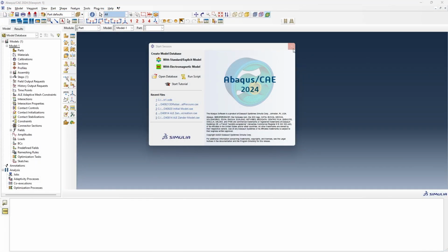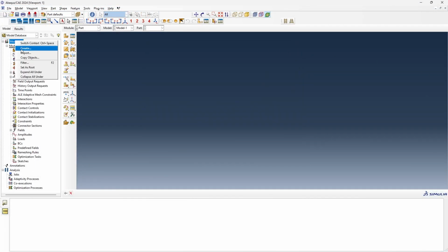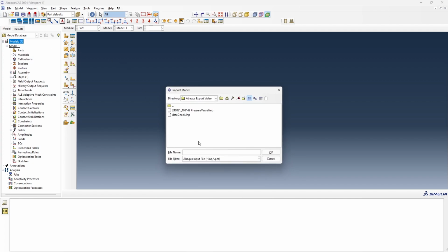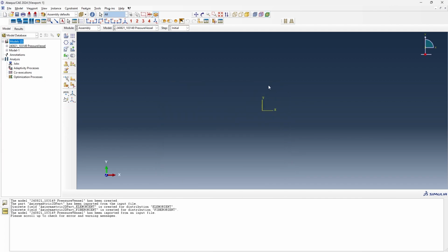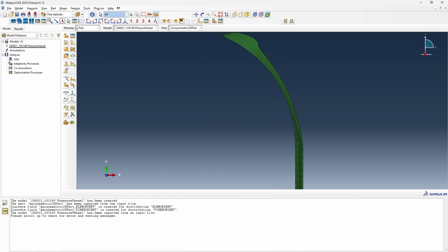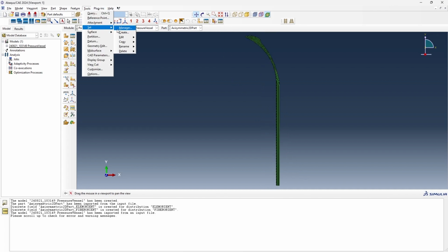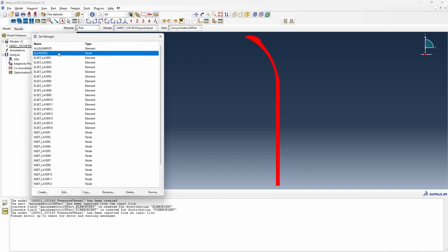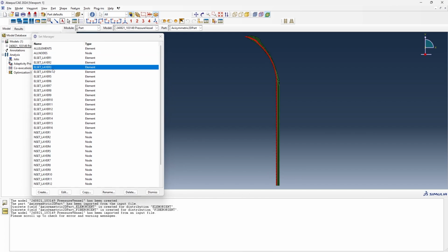We can now open Abaqus and import the 2D axisymmetric model. With importing the model, an orphan mesh will be generated. The imported part has element and node sets for the entire geometry, along with sets per ply. These are useful when results need to be queried per layer.